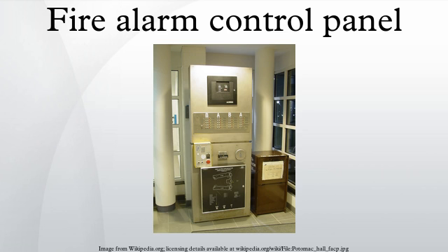Networking. The principle of networking involves connecting several panels together to form a system. Inputs on one panel may activate outputs on another, for example, or the network may allow monitoring of many systems. Networking is often used in situations where one panel is not large enough, or in multiple building situations. Networking is also an effective way to decouple systems to reduce the risk of a large portion of a facility going offline at any time due to system failure or maintenance requirements.